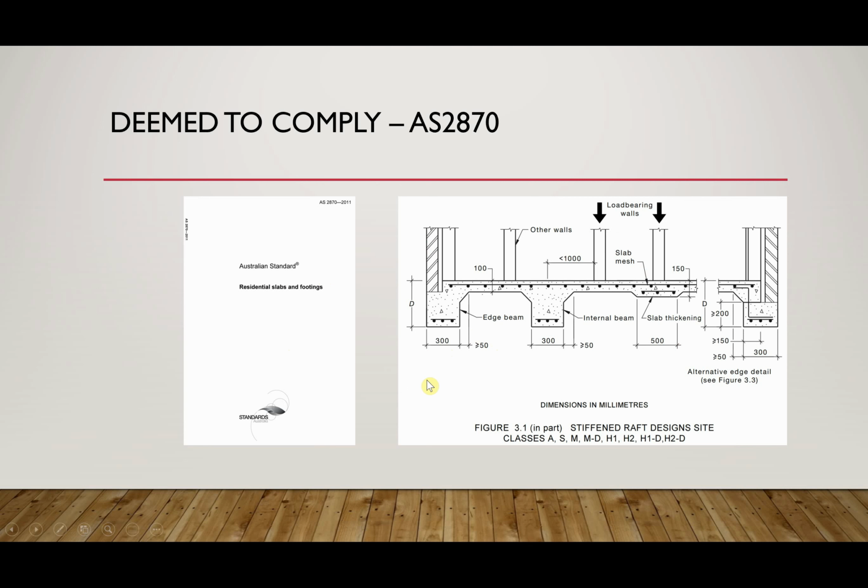So our footings are 300 millimeters wide, given here. The reason for that is if we go every 100 millimeters bigger than this, we have to put extra steel top and bottom. So there are lots of little things that I will just mention to you, but we're not going to go through in detail. Please also note, a key thing is your depth is from the top of the slab to the bottom of the footing. It's not from the edge of the rebate.